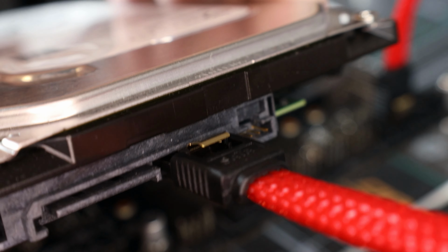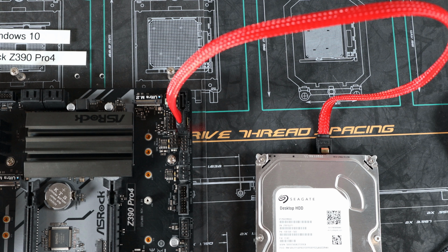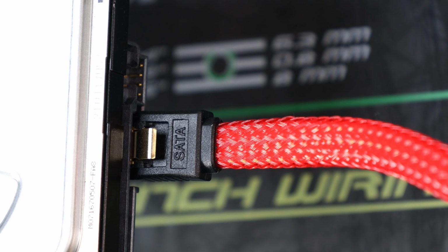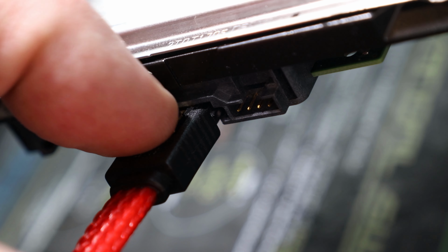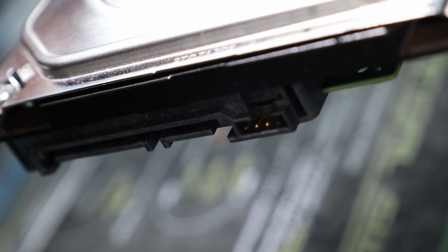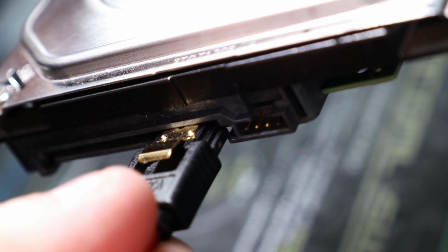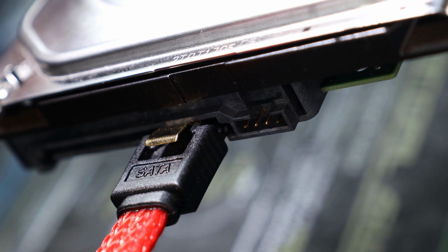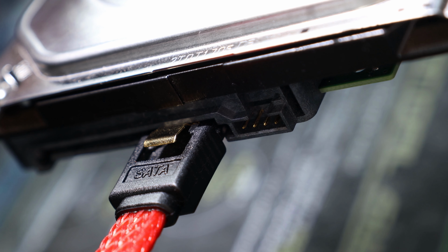To remove the connector, in some cases, you can just simply pull the cable out of the connector. In this case, this cable has a latch on the connector. In order to remove the connector, the latch needs to be pushed down. In most cases, the connector will go in without pushing down on the latch. With some cables, the latch will make it difficult to push the connector in. So if you are having problems getting the connector in, push down on the latch and try again. Some SATA cables will have a latch and others will not.